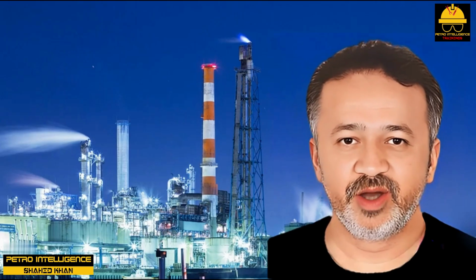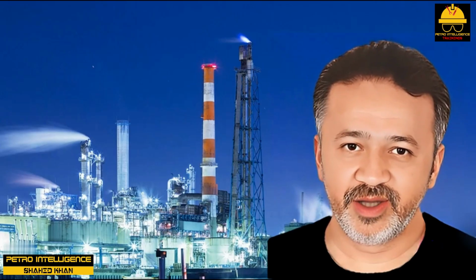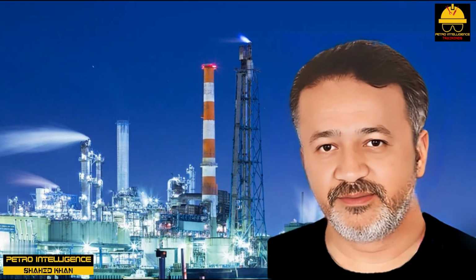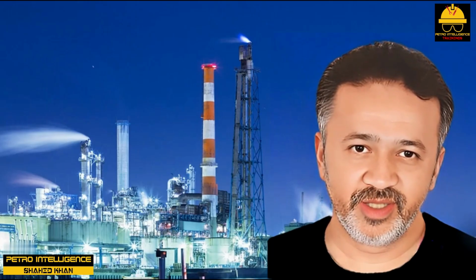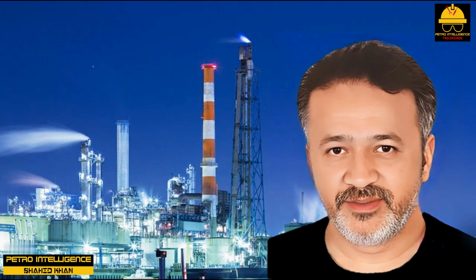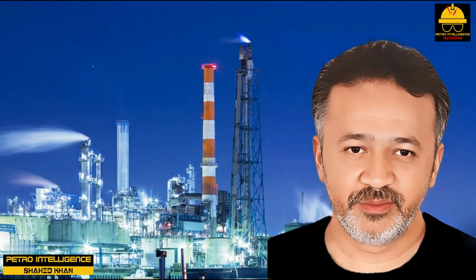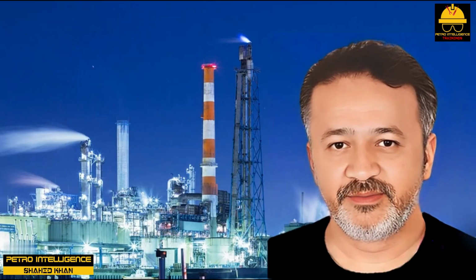This oil partly coats the refrigerant tubes. The heat transfer efficiency of the evaporator is reduced. Turbulence caused by the boiling of the refrigerant prevents efficient draining of heavy oil from the evaporator. However, if the refrigerant receiver has been designed properly, it can be used to trap out the heavy lubricating oil.